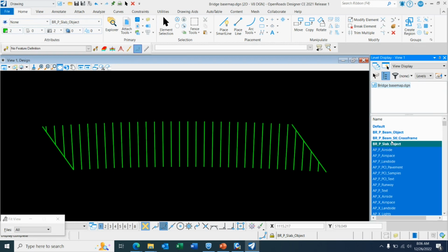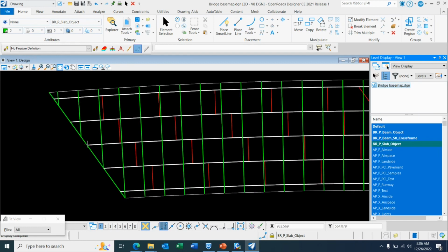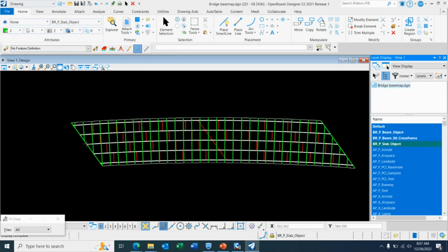Sometimes some unused layers show up in Midas, so remember which layer contains what. Also, I would like my origin to be at the mid of the bridge, right at the start point, so that it helps me to make a reference while working in Midas. So let's find the origin.